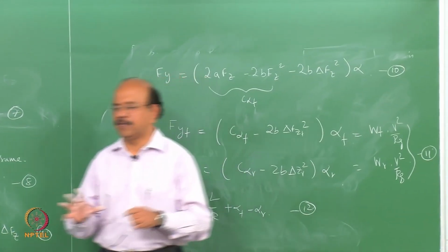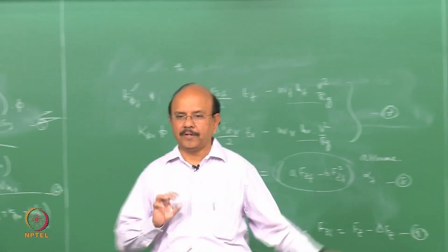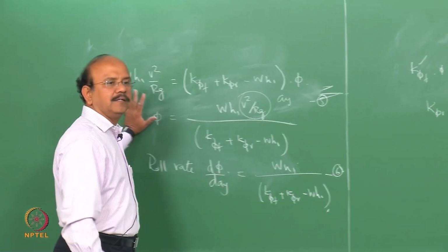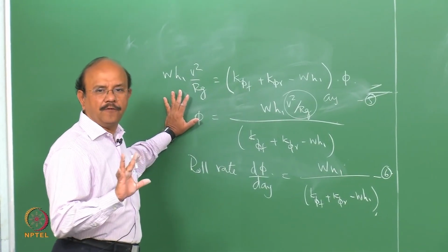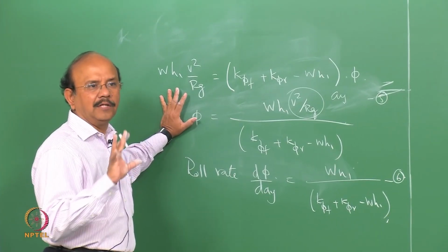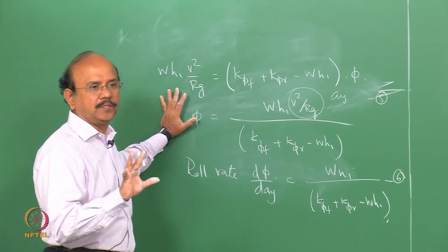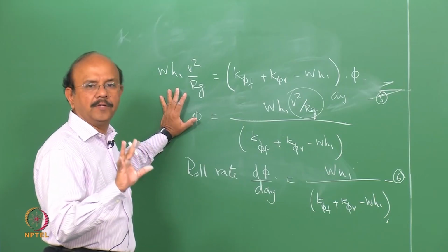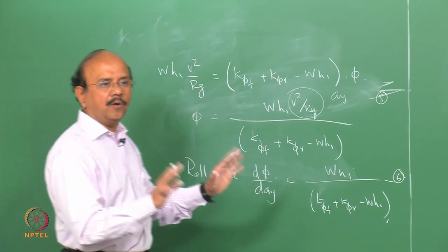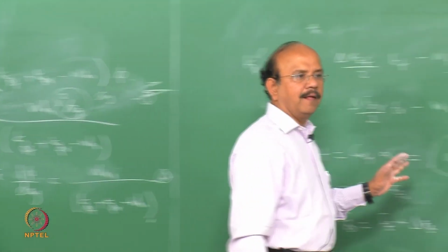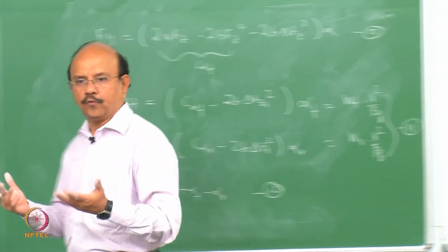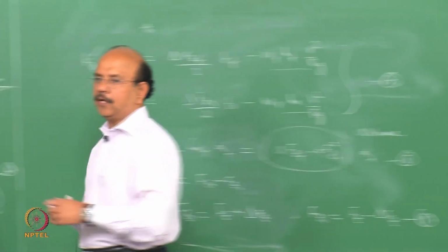So what is it that we essentially did? Just recapitulate, we will expand that in the next class. We realized that the load transfer is going to change alphas, and the load transfer is due to roll, and that the roll is controlled by what is called roll stiffness. And the roll stiffness comes from the suspension stiffness. So now using that and using simple equilibrium, due to forces that are acting in the body, we find out what is phi.